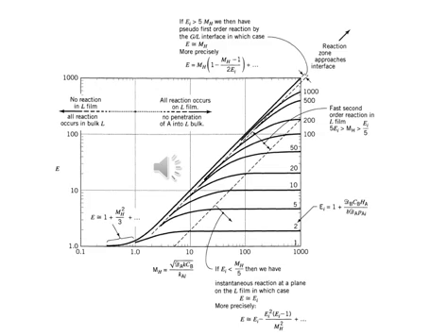Then we have the last region, which is on top, where EI is greater than 5 times the Hatta number. And in this case, our enhancement factor is equal to the Hatta number. We did not cover the 8 cases here in detail, but it is important for us to know these 8 cases and visualize what's happening.